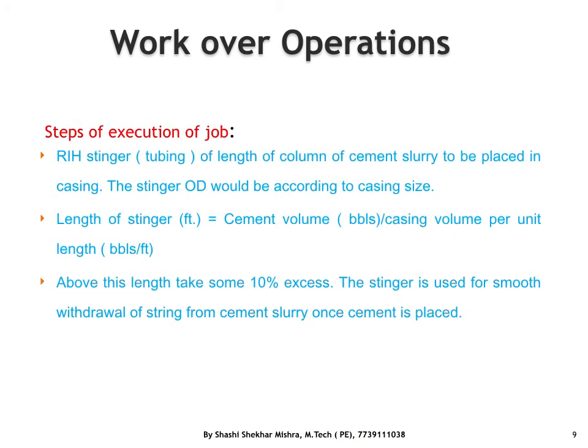Now comes the operation. In that we run the stinger, that is the tubing mainly, on the drill pipe, and place it just against the bottom of the perforation. If the sump is too much, we can place some high-vis pill also. Else we keep the open end against the bottom of the perforation.